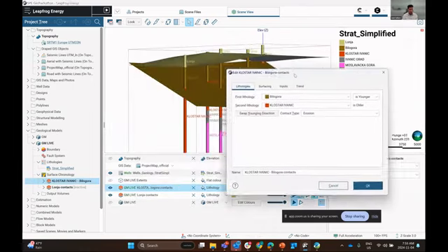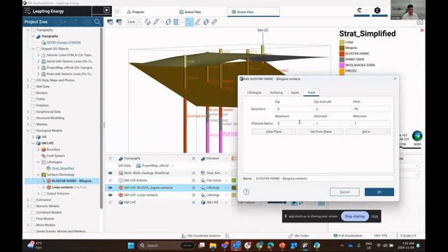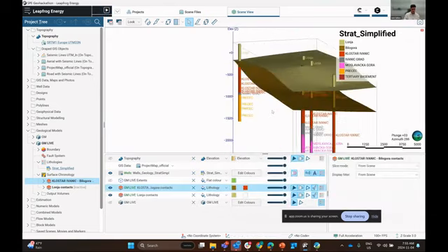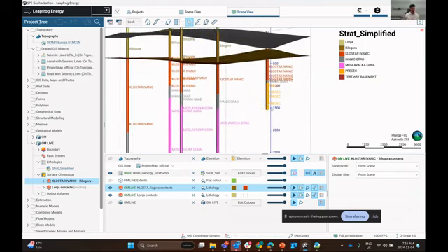Double-click, and we'll actually apply the exact same trend. A dip of 0, dip azimuth, and a pitch of 90 is essentially just flat. So you can use that user-defined plane, or if you wanted to just flatten your surface out horizontally, you can use the default direction of that plane. So we'll change the ellipsoid ratios to 5, 5, 1, and then that flattens that surface out. And again, we'll work from top to bottom.